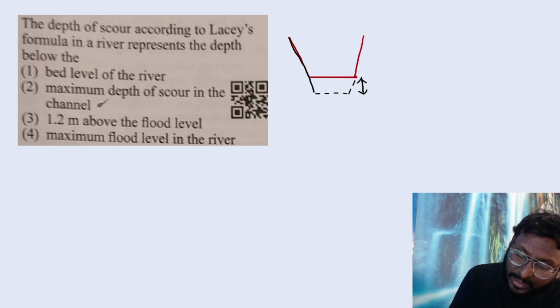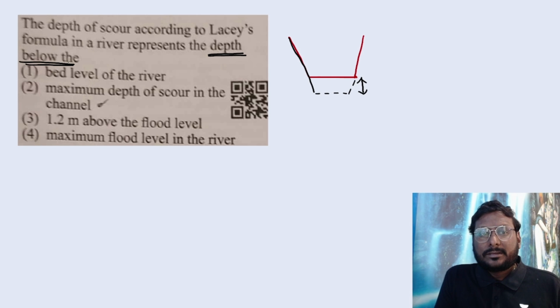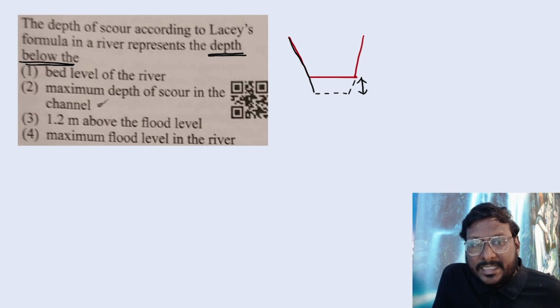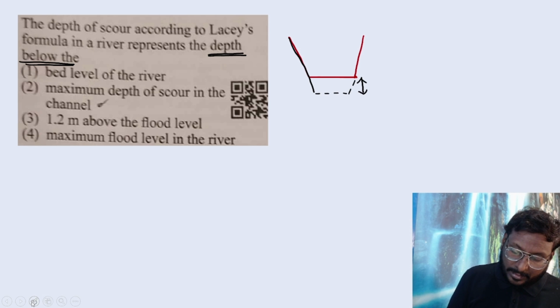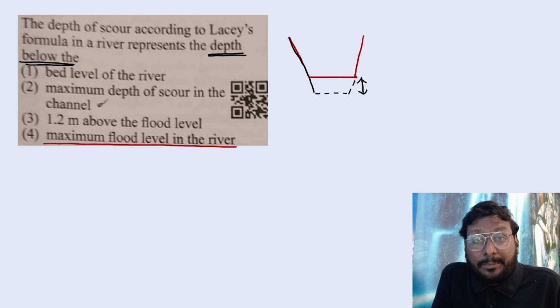So the depth of scour according to Lacey's formula in a river represents, they have mentioned, depth below the... While designing, if you are assuming it as a design, it is depth below the maximum flood level in the river.